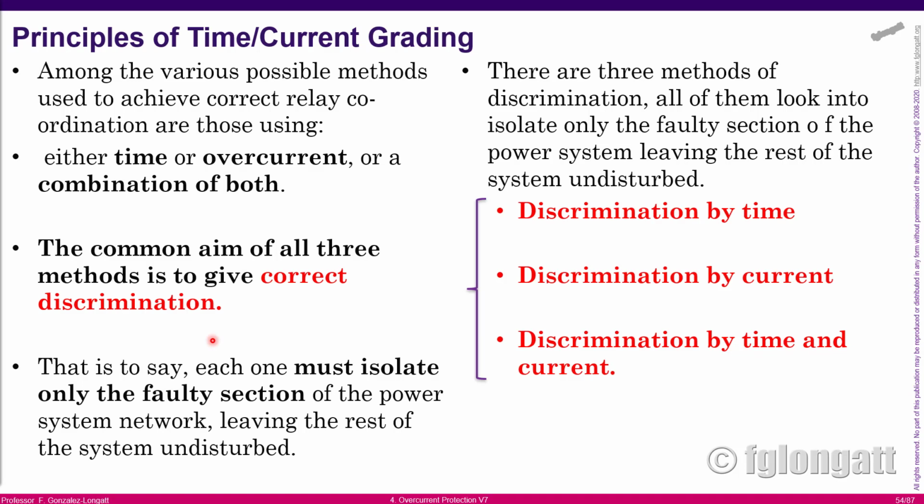But identifying the settings means that for one specific variable, what is the limit that defines the fault condition? I mean, from this value above, there will be a trip in the circuit breaker, because that is a fault condition. And below that value, that means that we are in a normal condition, that is a block.